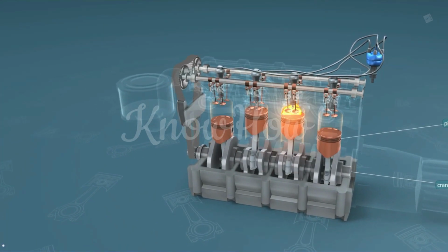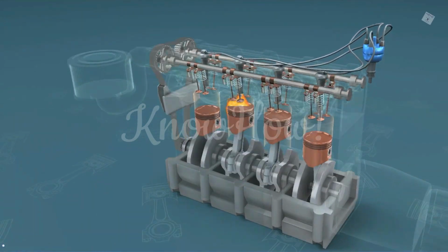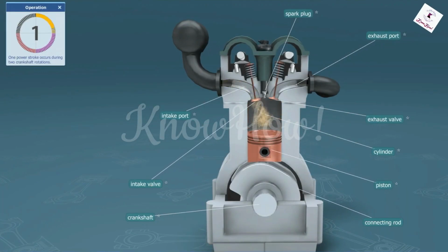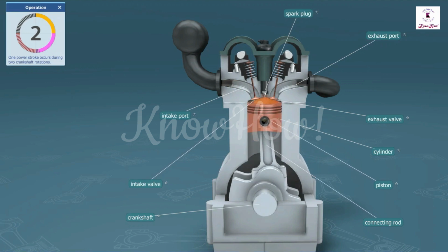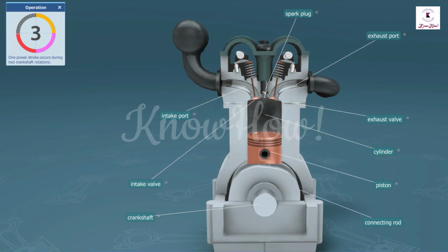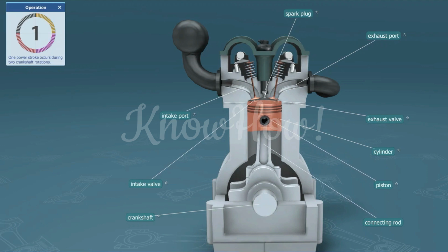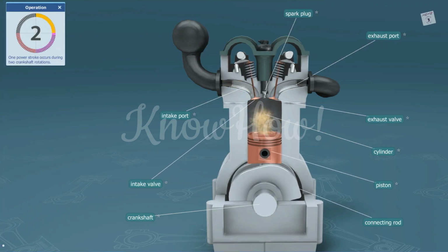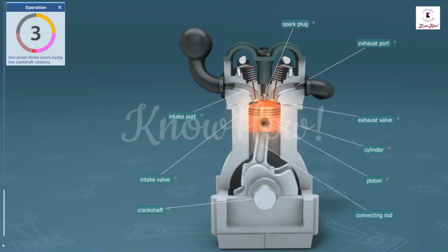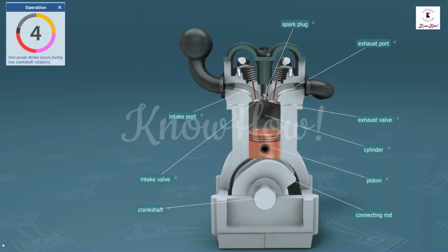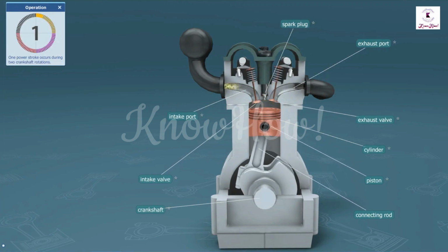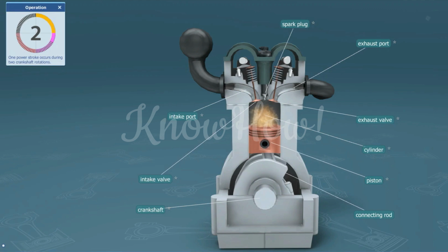The four-stroke process contains: 1. Intake stroke. The intake valve is open, and as the piston travels downward, this suction pulls the air-fuel mixture into the cylinder. 2. Compression stroke. Both valves are now closed and the piston compresses the air-fuel into a much smaller volume, preparing the mixture for ignition.